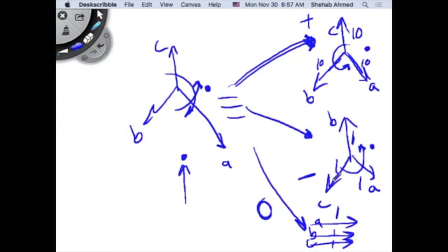You're also applying, at the same time, a negative sequence, but with a lower value. So what are you trying to do? You're trying to rotate the machine in the opposite direction. If you apply voltage, you will have current, right? So you will have current in the winding, but what is it doing? You're actually decreasing the torque. This is opposing the torque produced by the positive sequence, right? So you're heating up the motor. You're not going to get the same amount of torque. You brought the torque down, and what happened to the current? It went up, because you added some negative sequence current to your machine, right?